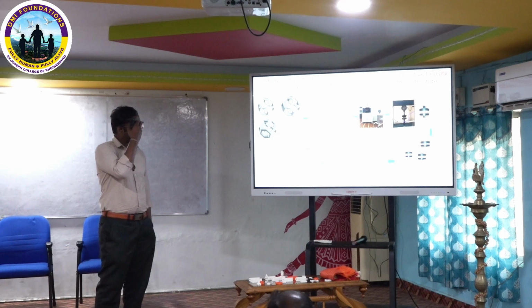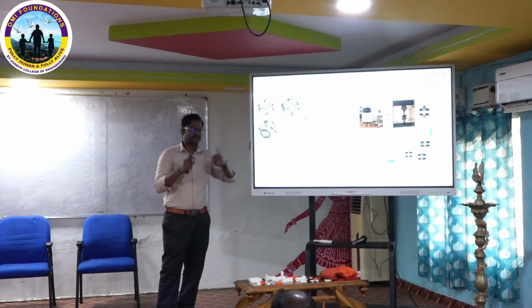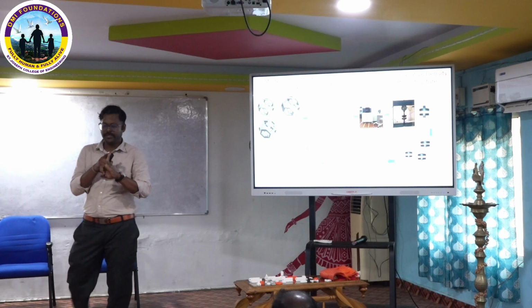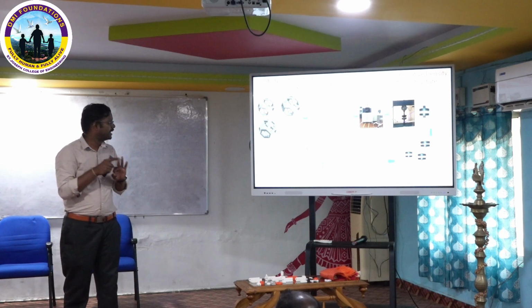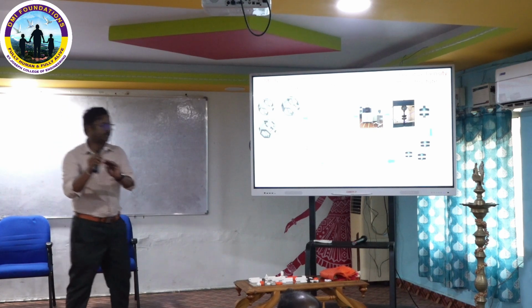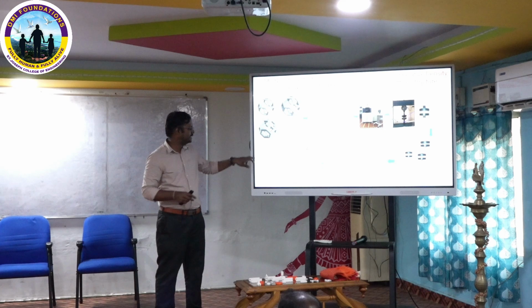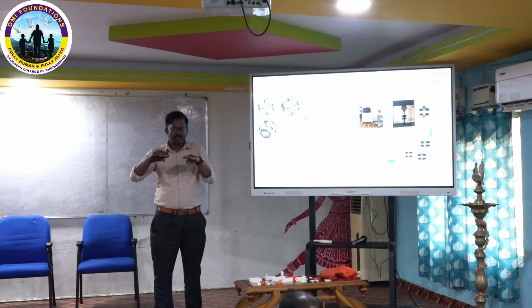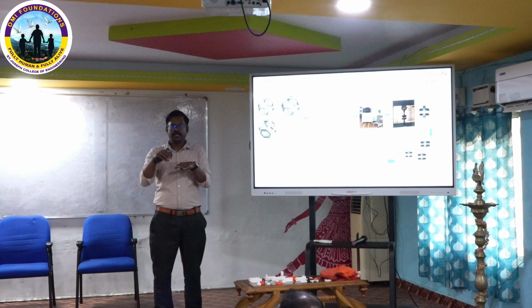In the laser parameters, there are particularly 240 parameters. I take only three laser parameters: laser power, laser speed, which is how fast it will move, and hatching distance. Why I take these three parameters is that they control the energy density of the laser. In a particular layer, how much energy density should be placed in the sintering process is the main thing we have to consider.